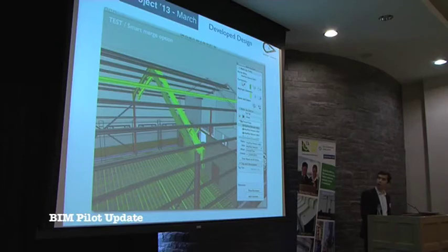I did also a test. I took his IFC file that was merged into the model, and I asked him to modify two elements, as you can see in clear light here. So you can do a smart merge option in any BIM application as well, so you can track the changes as they come in. So revised information is highlighted.